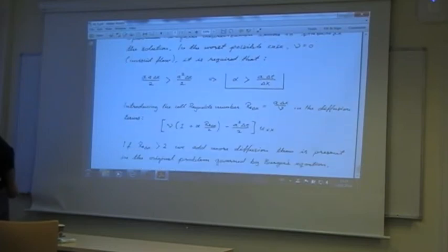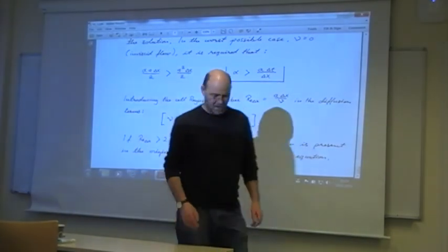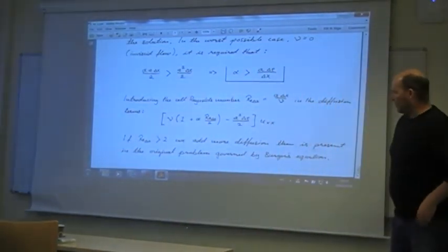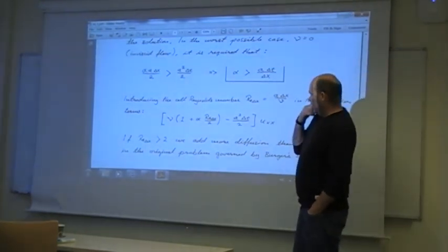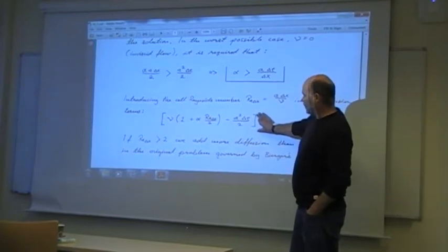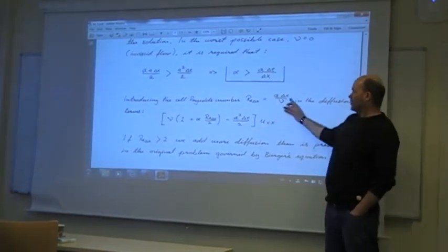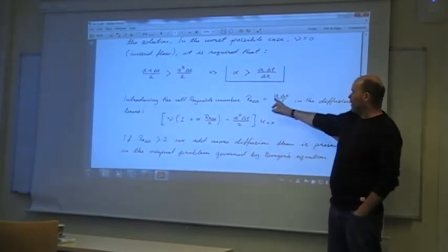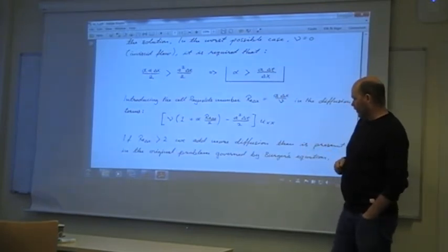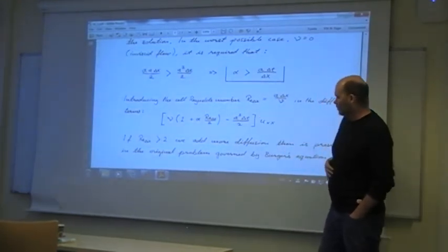Finally, if we have a mix, we have viscosity a little bit, and we choose more or less also the upwind scheme, and then we rewrite this square bracket, including all our diffusion mechanisms, by using this cell Reynolds number, sometimes also called a Peclet number, a local Reynolds number based on, here it's just this reference velocity A, but a local length delta x for the cell. Then you can get it on this form.